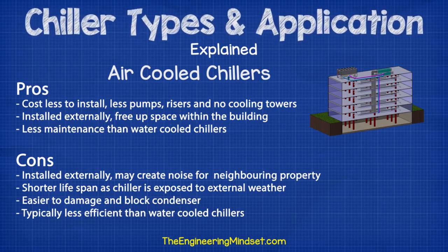Air-cooled chillers typically do not have as long a service life compared to water-cooled chillers because they are exposed to the sun, the rain, the frost, the snow, the wind, etc., and this will all deteriorate the materials. Air-cooled chillers can suffer from blockages much more easily. They can be damaged and they can also suffer from things like recirculation issues.